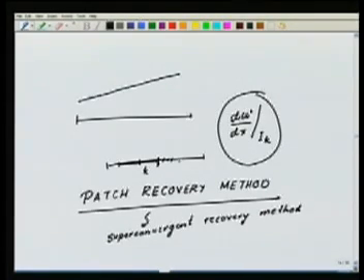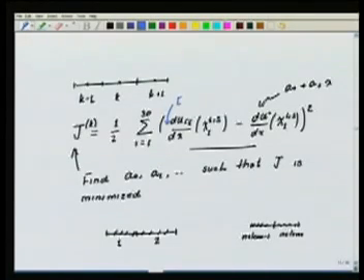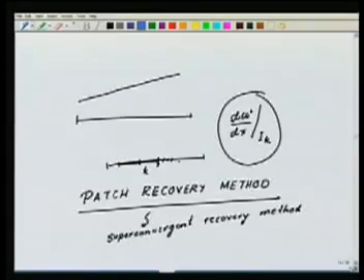Okay. There is another version of it where I can actually modify J to have here EA at the point x1I comma s. Okay, here I have taken 1, but in our sum we should have over all these integration points in the 3 elements which form the neighborhood or the superconvergence points. Here also I will have EA at x1I comma s. This is another way, an alternative definition of getting these superconvergent recoveries. Okay, especially when my EA is non-uniform but not transitioning. If it's a tapered beam, for example, then this will do the job.